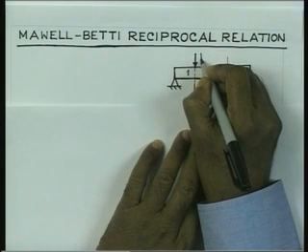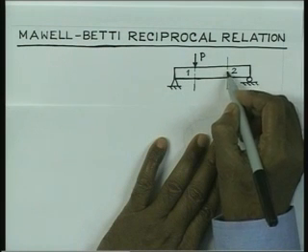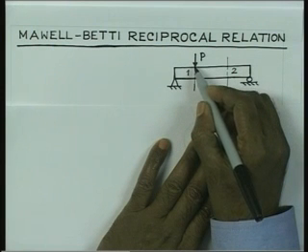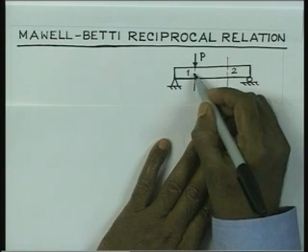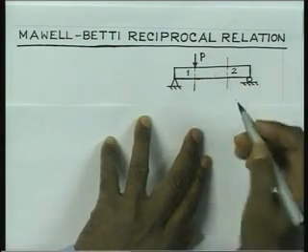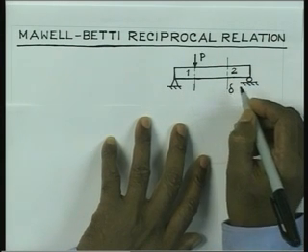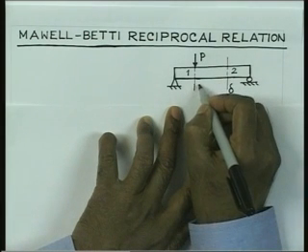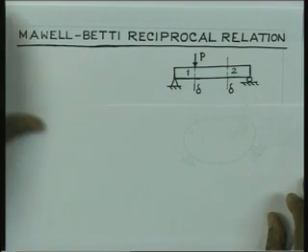1, a force is applied which is of magnitude equal to P, then the beam is going to give rise to some deflection at the point 2. If the force is now shifted from position 1 to position 2, then the deflection that will be produced at location 1 is going to be the same. So, what I mean is that if P is acting here and if we have a deflection here of magnitude delta, when P is shifted to location 2, we are also going to see a deflection delta at this location 1. So, this is the reciprocity relation.